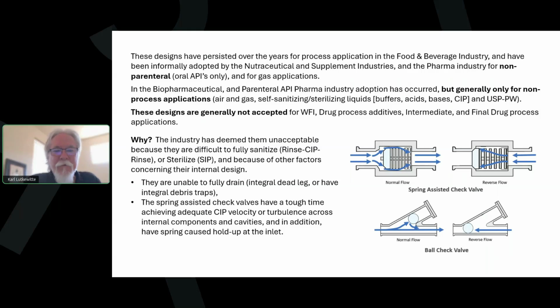Basically, he weighed the sterile vent filter before the test and after the test. He cycled these check valves, ours and a spring-assisted check valve like the one shown here, over about a month, just pulsing the nitrogen open and close. At the end of the test, he weighed the vent filter to see if there was a change in mass. And there was, on the spring-loaded disc in particular. There was a huge increase in weight, and what they found after evaluating the spring check valve were little bits and pieces that flaked off the disc. When the disc is forced into the seat, you get particulate generation.